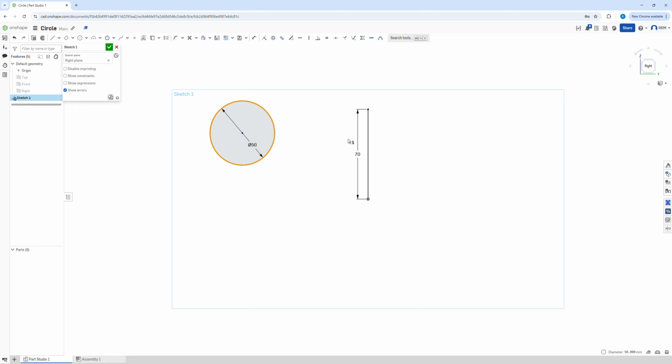I can then click on this and click on this, and I want this edge to be tangent. So I can go up to here, click on tangent, and what's happened now is, if I move that dimension to make it a bit clearer, this circular part is tangent to this line. Quite a useful shortcut dimension. This can now move up and down. So let's say we wanted this part and this part to be horizontal, and click H. It is now fully constrained at the top of that line.